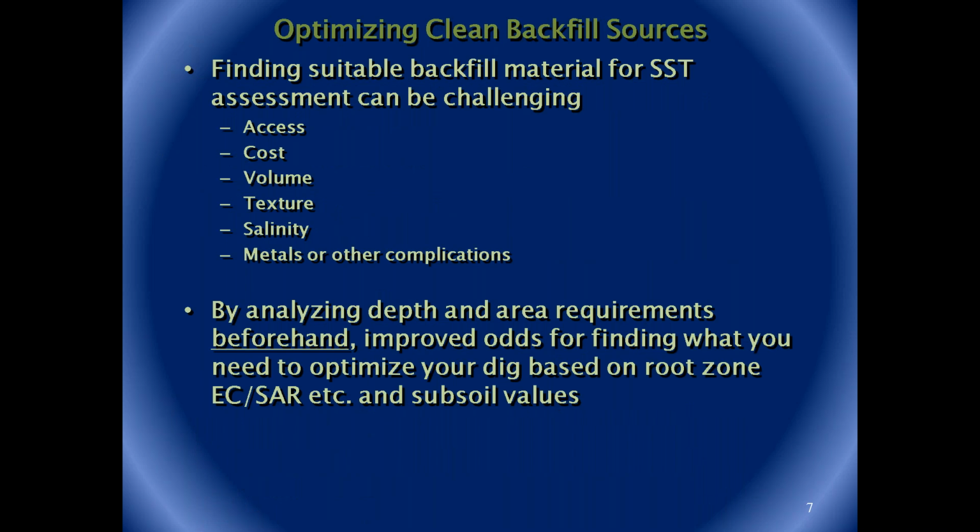And so I guess the other thing is backfill sources. This is really important, especially if you have a site with a diversity of background environments. Your backfill is tricky because you have to meet conditions: you have to have good access to it. There's the cost. There's the volume that you need, the texture that you need, the salinity requirements. You've got to watch out for other contaminants, metals, perhaps petroleum hydrocarbons, who knows. So there's a lot of effort, as everyone knows, that goes into getting good backfill material.